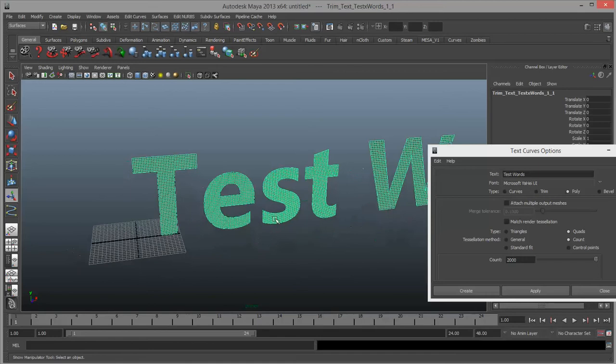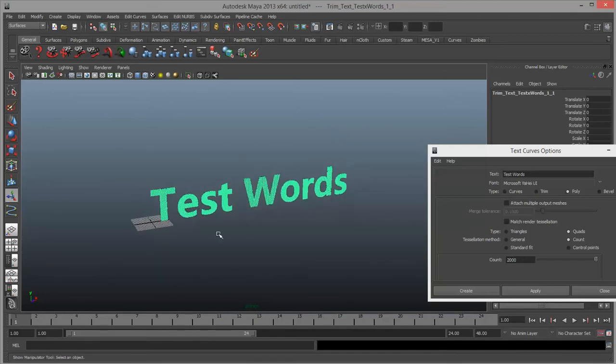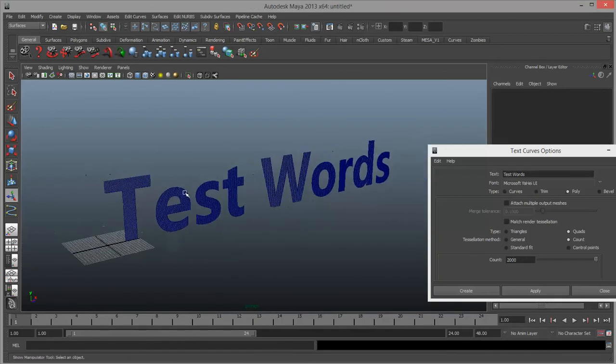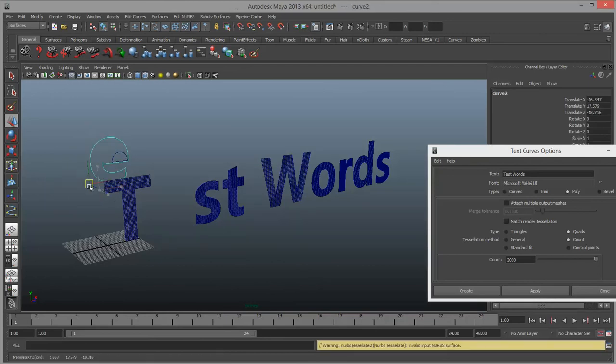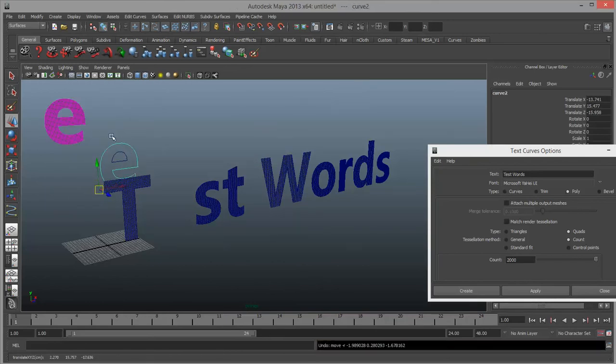Just really quickly, I want to show you that the way that you interact with this is a little bit counterintuitive. If you click a certain part of it, you will only get one letter at a time. If you drag over it, you'll get its letter and its curve, which will give it double transformation. So this part controls the letter. Actually, you can see I just broke it. Let me see. If I click on the edge and then click up to go up in the hierarchy, now I've got the apparently locked Bezier curve group.